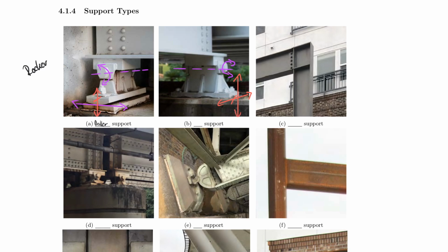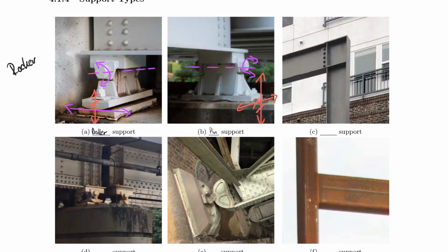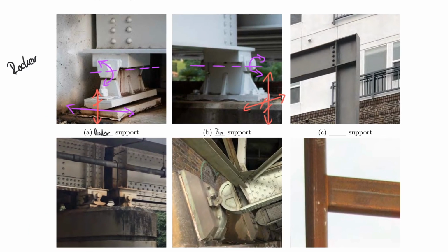So these are both restricted degrees of freedom, if you will, whereas the purple one here is still allowed to happen. Now, that one we call a pin, because the only thing that is free to rotate is the rotation, right? Or the only thing that's allowed to move is the rotation. So it rotates about that pin. So think of this axis as the pin. So you would say, hey, this one here has a pin too. Yes, that's true, but it also is allowed to roll along this axis.